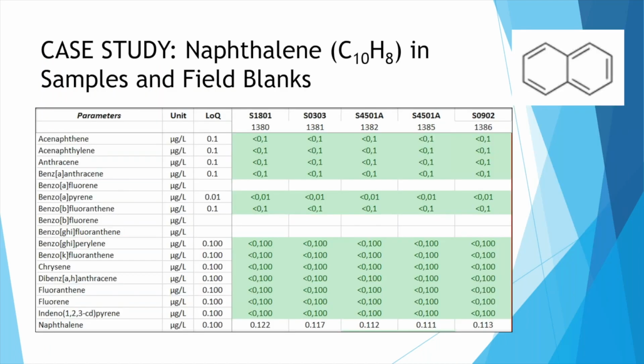Just a quick case study about field blanks. I was involved in an EU project in Turkey in the last 2 or 3 years, and it was a project taking groundwater samples from 100 monitoring points in central Turkey, and there were some issues that we found with contamination of field blanks. The way that this appeared first of all was from my review of the data.